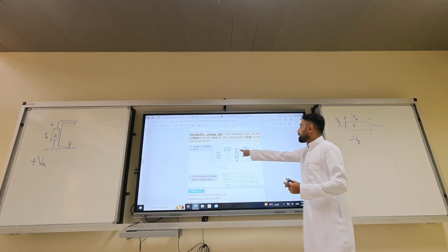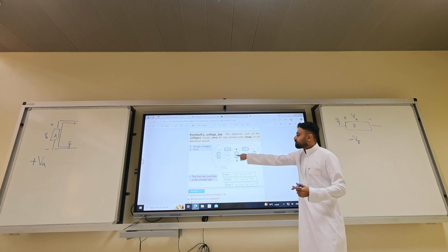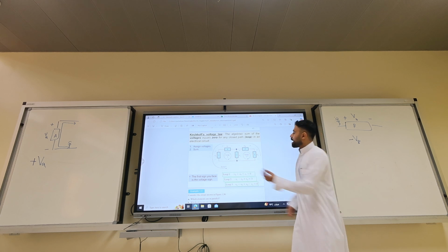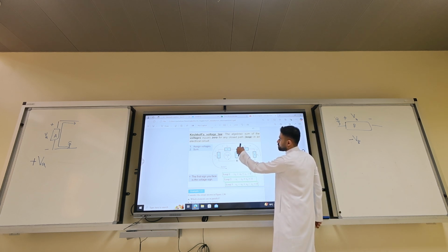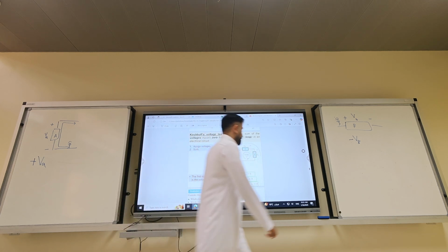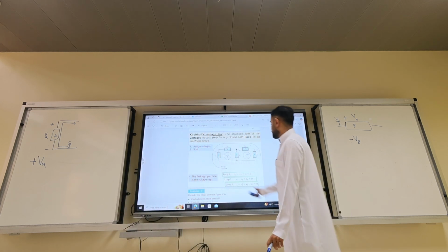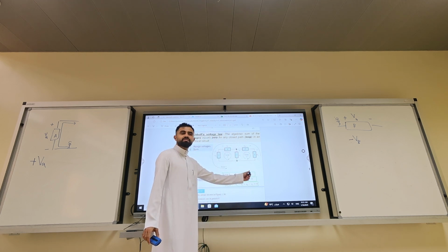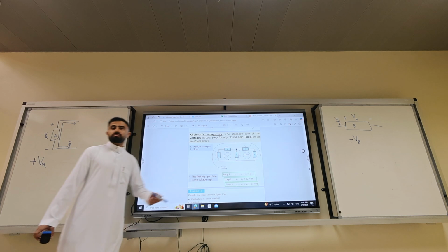Now, ending with D, I'm here. Is it a voltage rise or voltage drop? No, I'm going from top to bottom. Drop. So it's going to be a negative. So what the book tells you is minus VA plus VB plus VC. Don't follow the book.